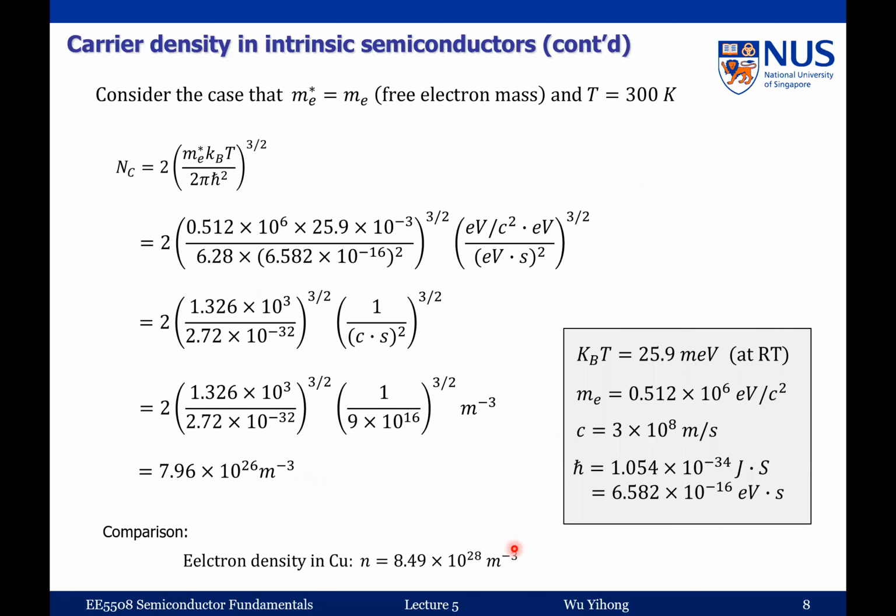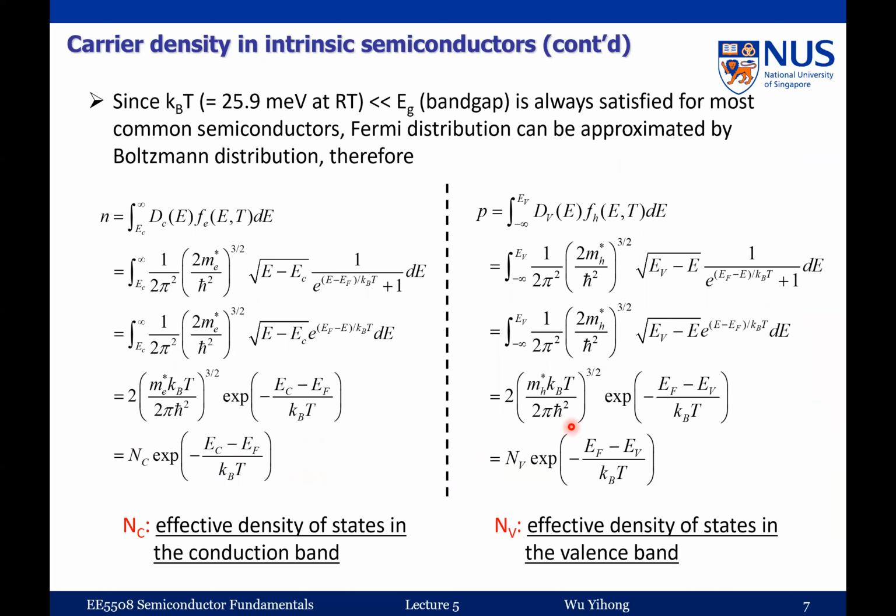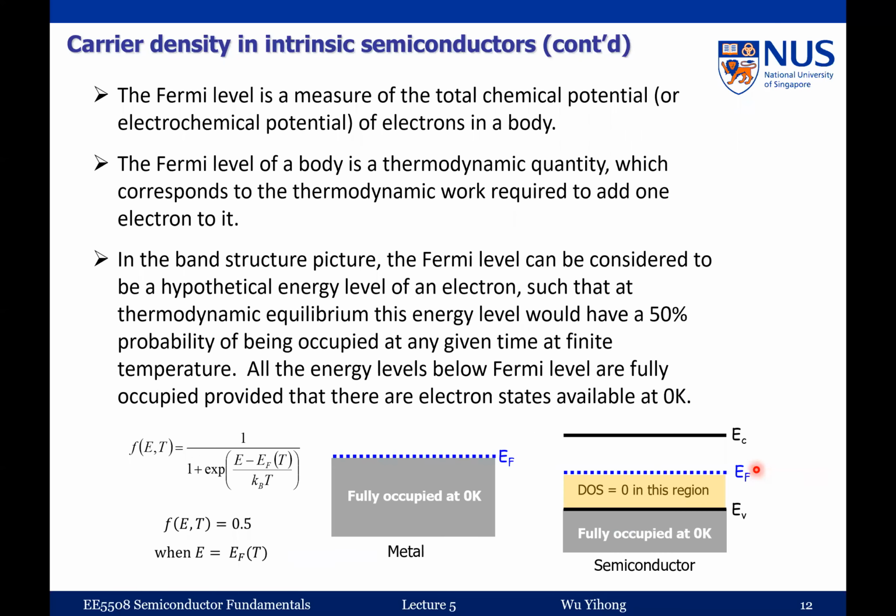carrier concentration, and what we derived, you can see this exponential function is also in 1/T. So that's why when you use 1/T and a log scale, you can plot this as something proportional to 1/T. This means log P is proportional to 1/T, and log N is also proportional to 1/T. But after you take the log, there's a negative sign here, right? So that's why the slope is always negative. So that's how we plot it.